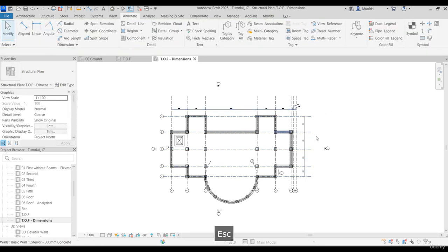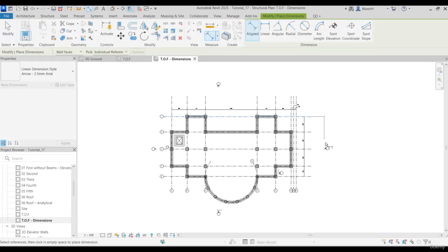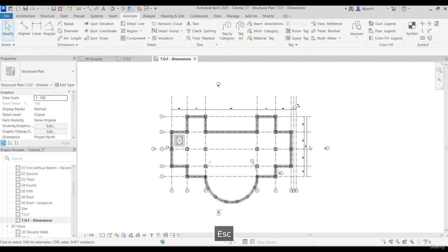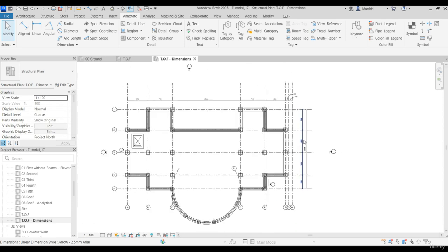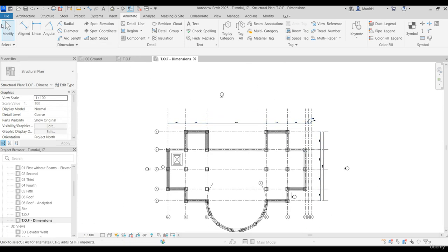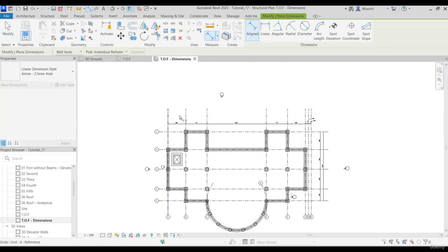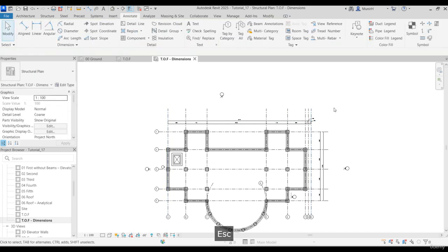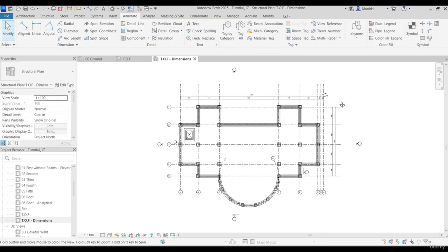There is a nice tool in Revit: if you do an aligned dimension from the beginning to the end, it snaps to the right place. So as you can see, this is how it's done. You can do the same thing for the vertical and the horizontal as well. You can see the snapping. It snaps to the right place, which is a very nice tool.